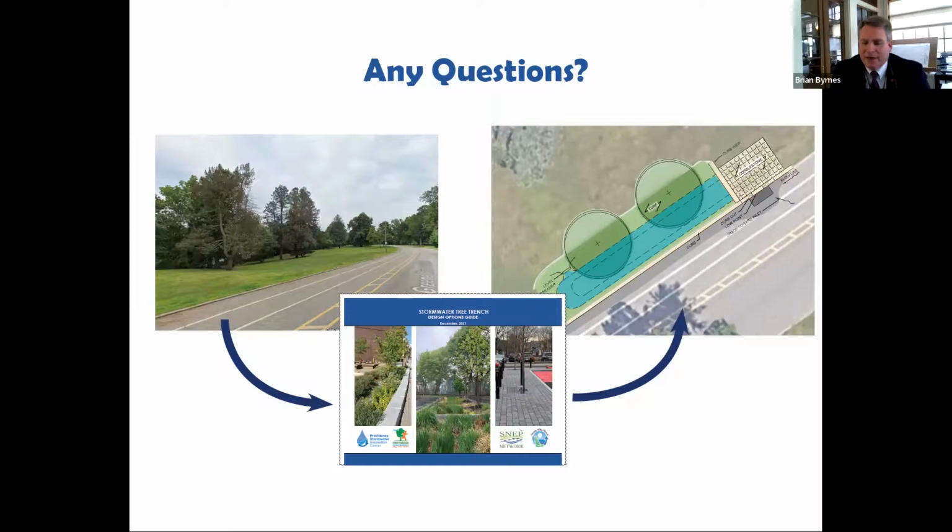And I think there's another important point when we're talking about plant material. The guidelines for designing plant material has been that you need to put plants in the basins that are going to survive in water. So we refer to it as trees that like wet feet. The reality is our weather patterns have changed and we don't get the 1-inch moderate rainstorms where these plants are in water all the time. We get 4 inches of rain in a 48-hour period. Most of it flows through this practice and potentially out the overflow. And then for the most time, these plants are in more dry and arid conditions.